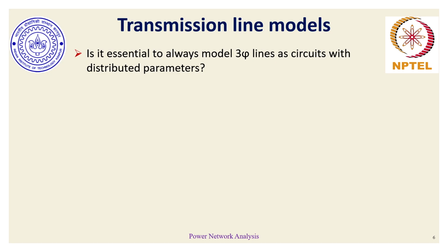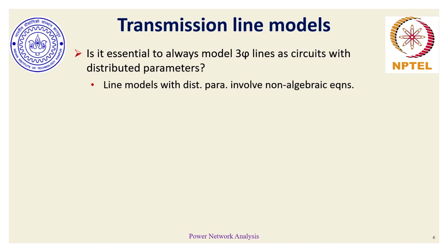Where the answer is no is because transmission lines, when they are modeled as lines with distributed parameters, the relevant equations that would come up, not in today's discussion, but hopefully in the upcoming 4th or 5th lecture in this particular module, we would understand and see that line models with distributed parameters will involve some non-algebraic equations. To be specific, these equations would be differential equations. If we talk about these equations in phasor domain, then yes, these would be differential phasor equations.